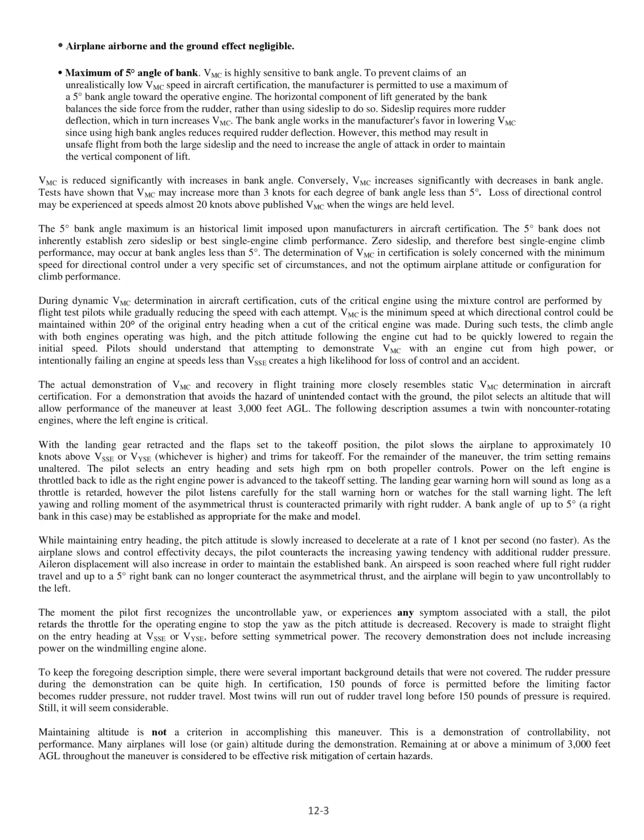Maximum of 5 degrees angle of bank. VMC is highly sensitive to bank angle. To prevent claims of an unrealistically low VMC speed in aircraft certification, the manufacturer is permitted to use a maximum of a 5 degrees bank angle toward the operative engine. The horizontal component of lift generated by the bank balances the side force from the rudder, rather than using sideslip to do so. Sideslip requires more rudder deflection, which in turn increases VMC. The bank angle works in the manufacturer's favor in lowering VMC since using high bank angles reduces required rudder deflection.